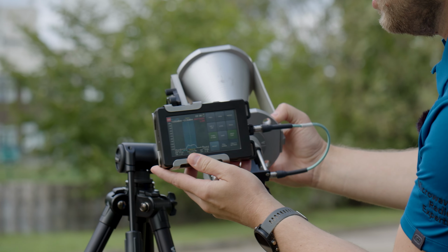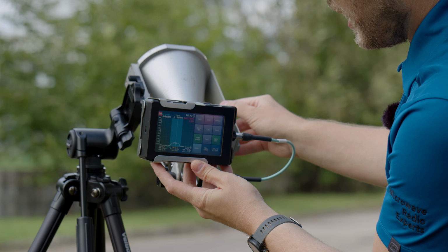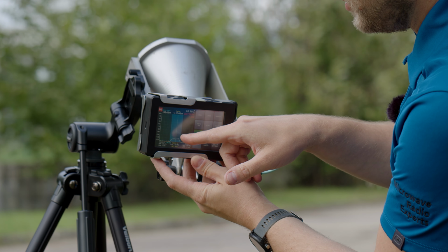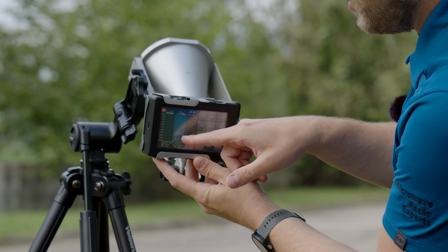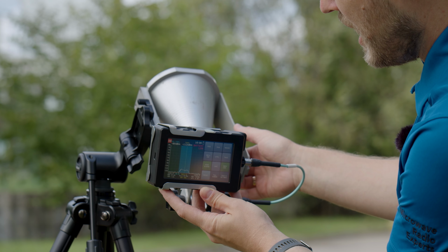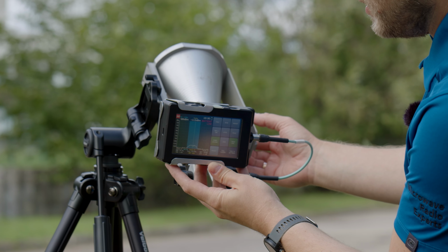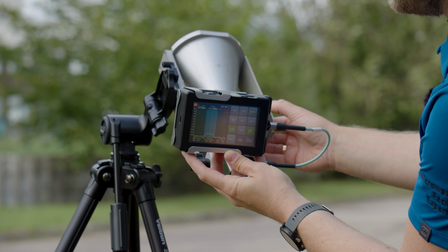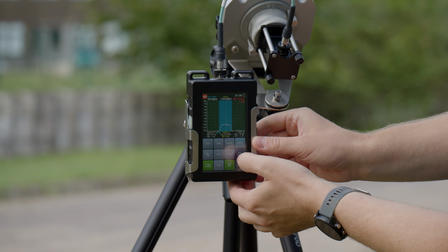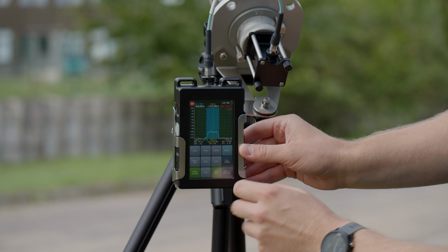Now we rotate the antenna, and we see that the power of the signal that we're measuring is now somewhere in the area of minus 98 dBm. So we can see that the signal that we are measuring is in the vertical polarization. And as we turn it back to the vertical polarization, we see that the signal level increases.